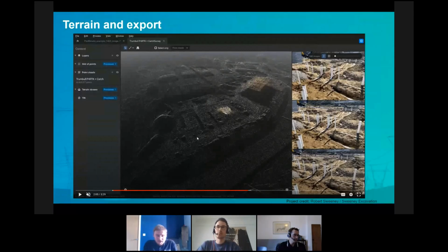And just going back to what you said, Nate, about LiDAR, like you, I come from very much a photogrammetric background and really like photogrammetric data sets. I think they're brilliant. There's always this buzz about LiDAR, and we get asked about it quite a lot, and I have to stress the point that it's not the be all or end all. Photogrammetry, I'd say in 80% of applications, works perfectly. There are other areas where LiDAR does come into its own, like vegetation penetration to a certain degree, or power line surveys to measure line sag. Yes, LiDAR really comes into that.